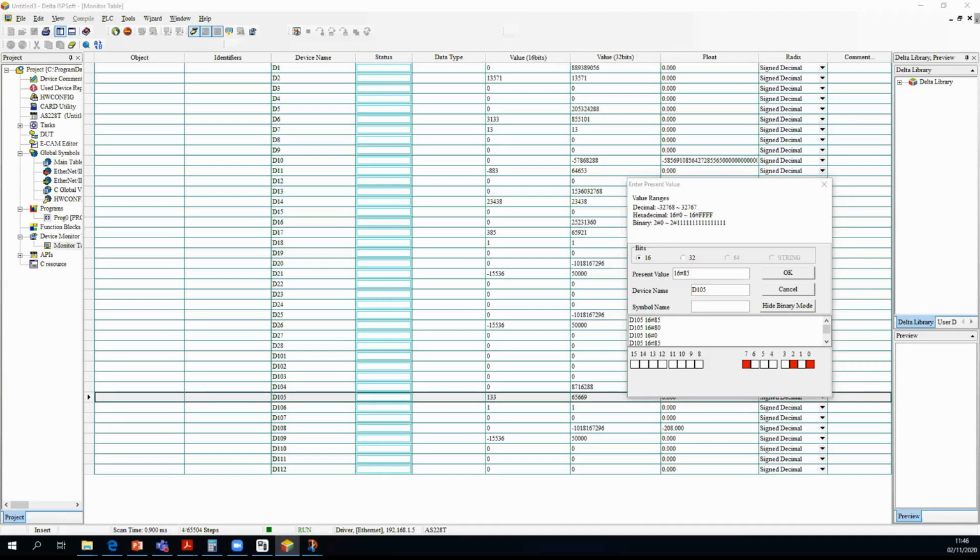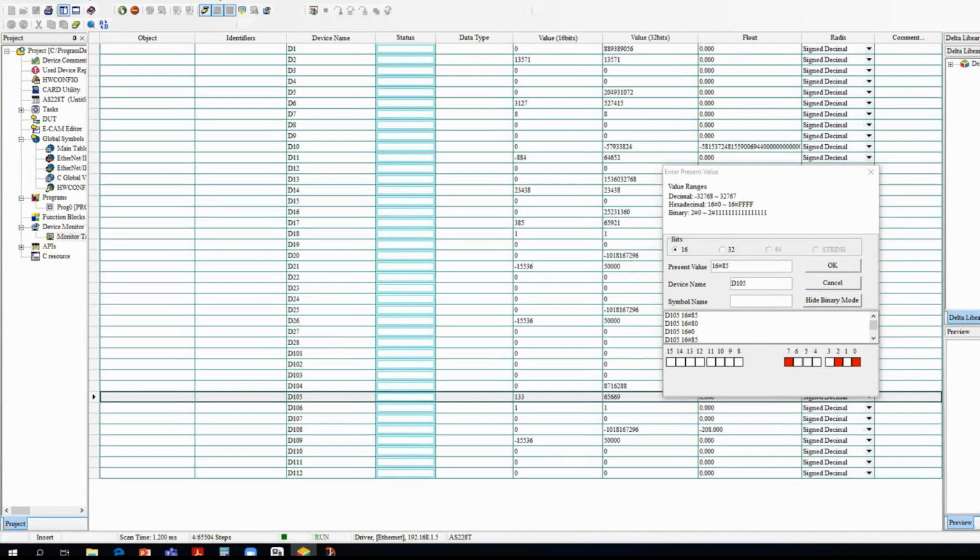So in this demonstration, I just started directly with the motor pre-configured. But if you want to do positioning, then you absolutely have to enter the motor nameplate, do an auto tuning, set the encoder details into the drive, and then set the drive to run in field-oriented control for PG cards. So let me see if I can just show this.